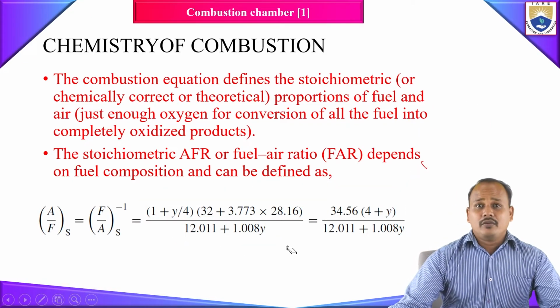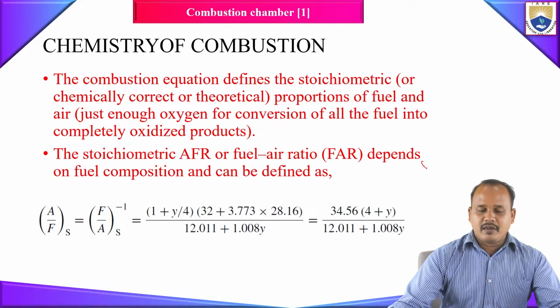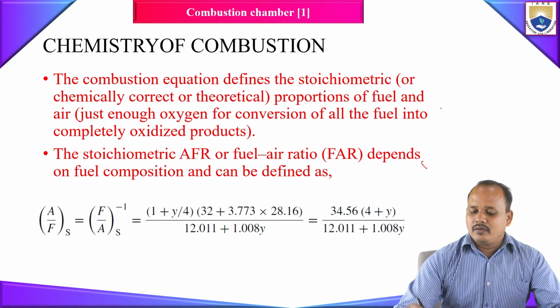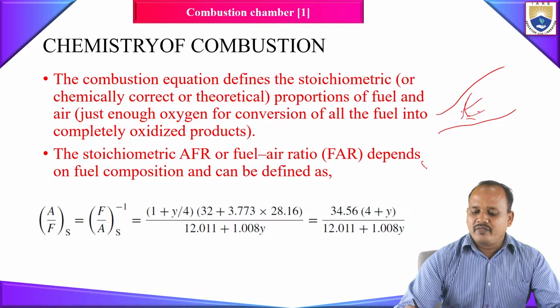So as long as we know, for example, when the airflow is entering inside your combustion chamber, we have seen the snout separates your flow into primary and secondary air. The secondary air goes through the space between your liner and casing. Your primary air passes through the swirl vanes, right?